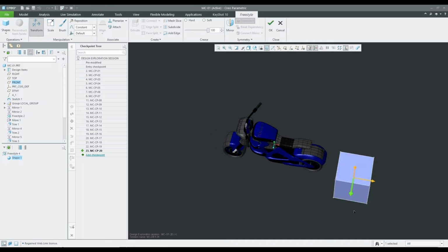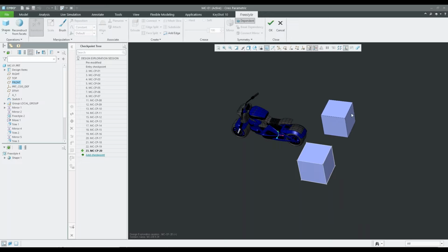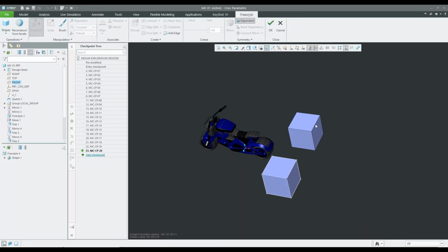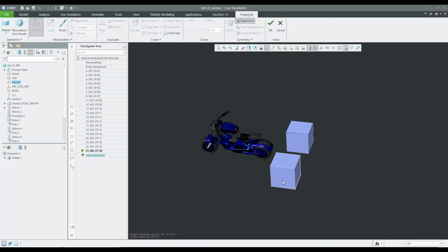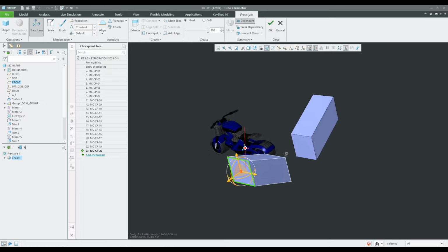Now, for example, if I offset this cube and I want to mirror that over the front plane, I can grab the whole cube, go to mirror, grab the front plane, right? So now we have 2 cubes, one in front of the front plane and one behind it. And now, just like before, I can go in here, start to sculpt. I can adjust geometry on this side. It'll update on the opposite side.